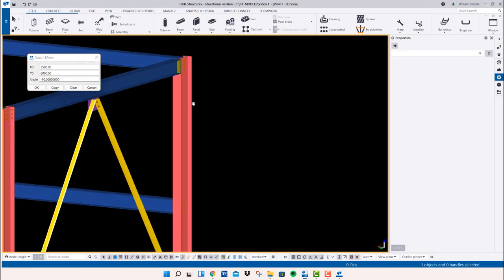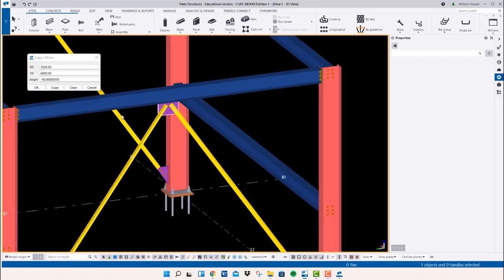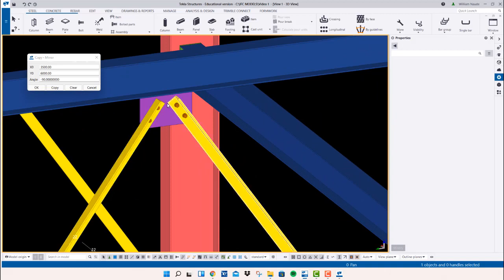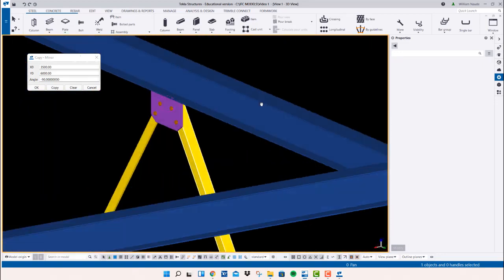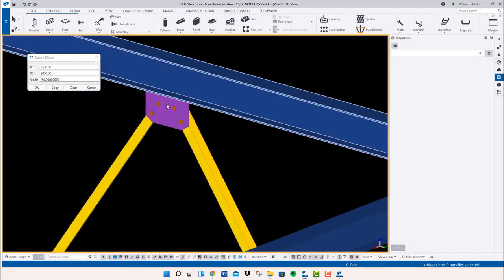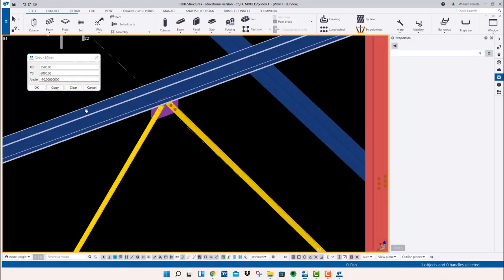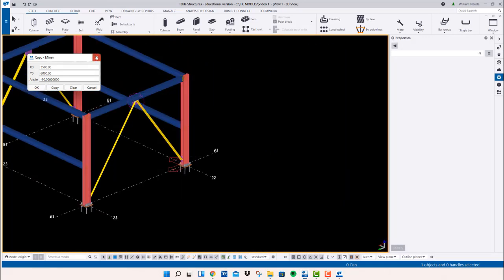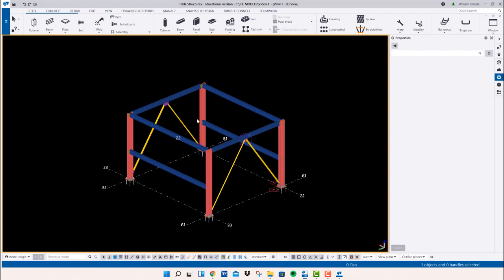Now, if I just rotate, it will rotate weird, as you can see, because this is the point. So where my mouse is shown, so right there, I'm going to hold Control Shift and then the middle button. I'm going to rotate, and it chooses that point as my rotation part. And now I can just rotate around that by holding in Control and the middle button to rotate. Right, so there we go. There we've placed in bracing beams and columns with their connections. So this is just a quick basic on how to work on a model of